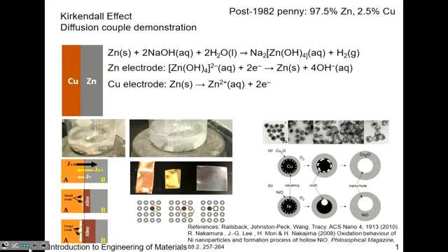So what people have looked at is either copper and oxygen. So you remember the discussion in the recorded lecture that in a ceramic system, the cation would diffuse at a different rate than the anion. And typically the smaller cation will diffuse more quickly than the oxide, right? So you have copper oxide or nickel oxide, the cation, the copper 2+ or the copper 1+ or the nickel 2+ will diffuse in one direction at a different rate than oxygen going in the opposite direction, okay?